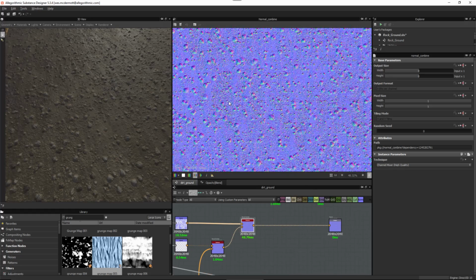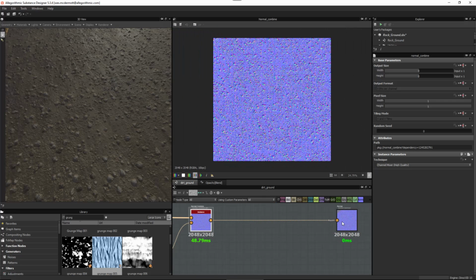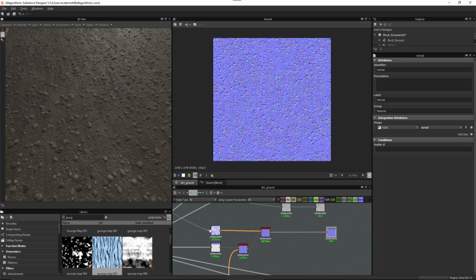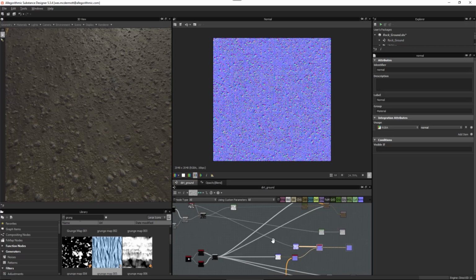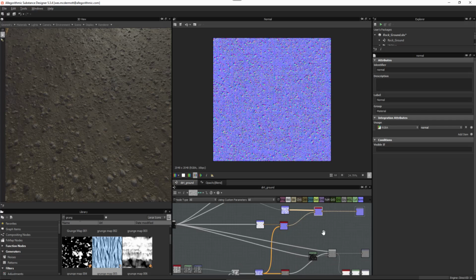For this normal map, you can see it's 16-bit at this time, so we're just going to output it 16-bit. This will actually get demoted to 8-bit once we're inside of Unity, but I'm not doing any of the processing here towards the end. I'm just outputting this again because, like I said, all of the maps we're working with from this node on are all 8-bit. So we're still optimizing our processing at that stage.